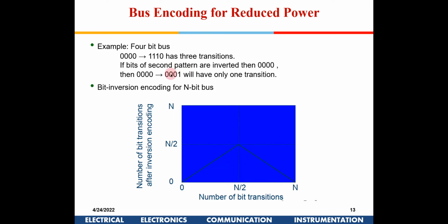Now when I am inverting the bits and sending them, you see the bit inverters don't consume that much power, but the bus capacitance is very high, because the bus has extensive routing. It could be within the chip, or outside, between chips communicating with each other on a motherboard. So we have to target minimum activity on these bus lines, because they are huge capacitances.